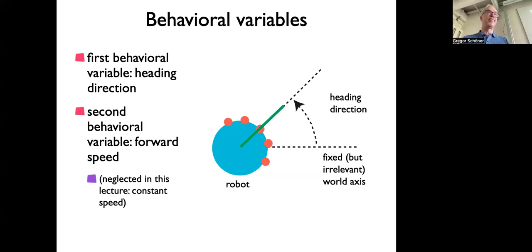And that's your heading. You can say it's the heading relative to the robot. The robot is oriented at 30 degrees, but you can't say, this is my heading. You see that heading would be constant. If I turn towards the thing, the heading is 0. So the heading is really relative to some fixed reference frame.